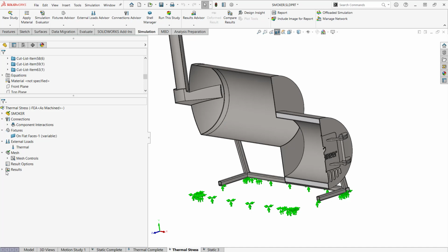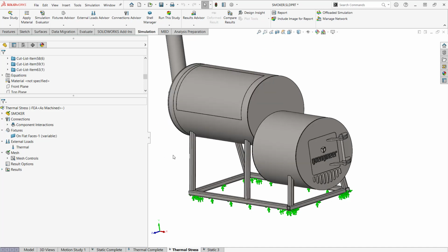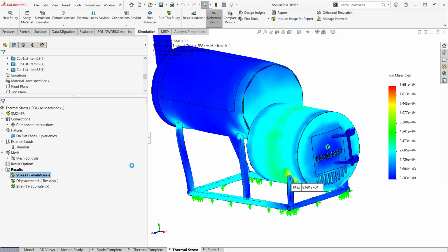Yeah, pretty straightforward, but just different ways that you can take advantage of the different levels of these tools. So SimXpress, no temperature data, but we could do pressure. Sim Standard, we could just apply a straight temperature on faces. And then with Sim Pro, I can do a thermal distribution and import that in.